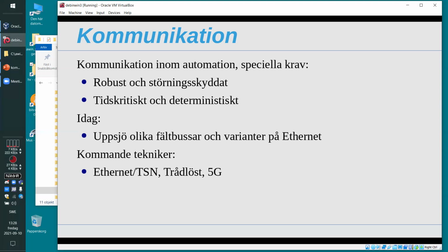So if you could use Ethernet even in the time-sensitive parts, it would save money, really, and it's more well used and well known. So many field buses have introduced variants that can run on normal Ethernet as well, but it's not normal Ethernet; it's sometimes their special kind of Ethernet.